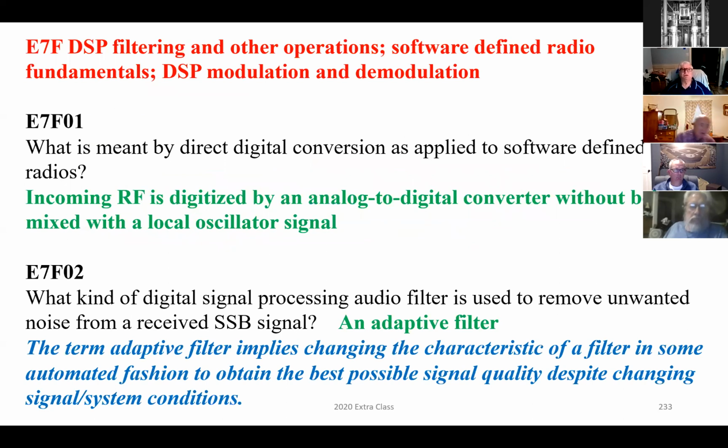Okay, next section is DSP filtering and other operations. Software-defined radio fundamentals, DSP modulation, and demodulation. Okay, what is meant by direct digital conversion as applied to software-defined radios? Incoming RF is digitized by an analog to digital converter without being mixed with a local oscillator signal.